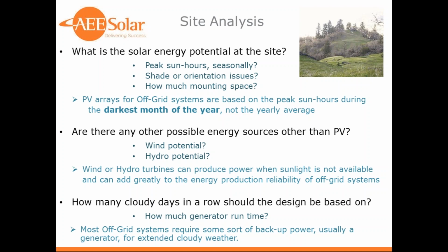We need to find out how much space, of course, there is to mount a PV array. And PV arrays for off-grid systems are, again, based on the peak sun hours during the darkest month, not the yearly average. And one thing when siting an array is to make sure that you have as much wintertime sun as you can get at the site.